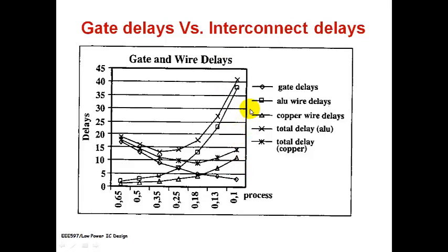This actually depicts the effect of introducing good conducting copper wire in place of aluminium wire. If we still want to reduce the wire delay, even better conductors like gold and silver could be used, but all the same, the contamination of the oxides and how the foundry process is going on will determine the feasibility of such an attempt.